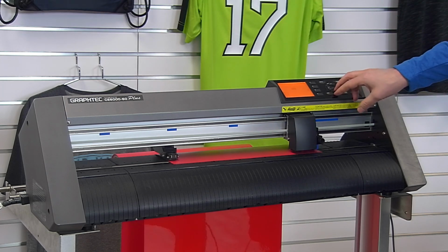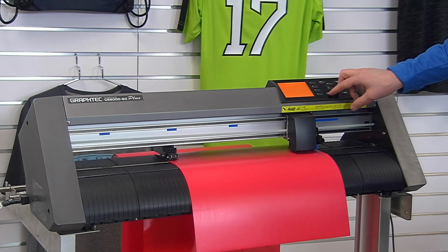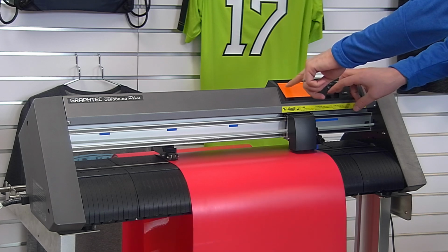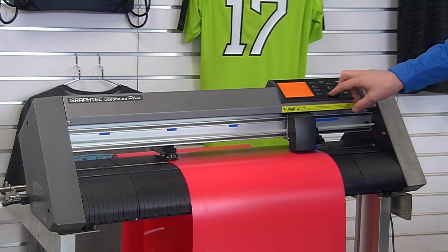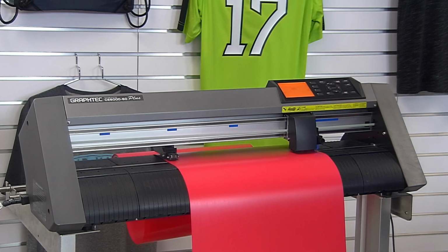So with this now, I like to advance my material through the cutter to see how long I can go. So I'm holding the down arrow key. I'm going to hold the fast button with the arrow key on the GraphTech, and that's going to start to feed my material, and I'm reading my X axis, which is the length of the material. Right now I'm up to 16 inches. I'm watching it against the pinch rollers. It's still looking straight. There's 40 inches, 50 inches, etc.